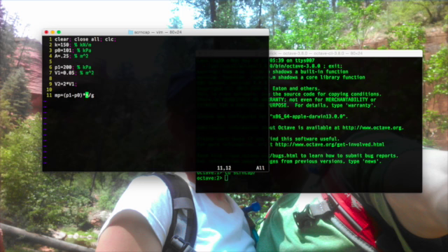So if I have a kilopascal and I multiply it by an area, I don't get a newton, I get a kilonewton. And then if I divide that by g, which is meters per second squared, I'm not going to get out kilograms. I'm going to get kilograms times 1,000.